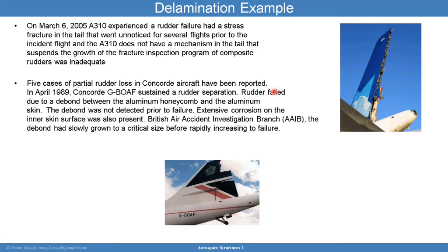You also have other failure mechanisms that have caused rudder failures, and those are delaminations, flaws between the core and the face sheet. What I want to describe here is a situation where you have a honeycomb core system in which air can be inside that core. When you manufacture an aircraft on the ground, you could entrap air at 14.7 psi, or 1 atmosphere, inside.